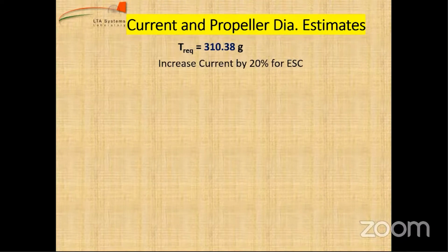So we start off with a thrust, and there's something more. Every electrical motor that you have. First of all, how many electrical motors do we actually have in our airship? Do you remember? How many motors do we need? We will need 3 motors. 3 motors, correct. Can you please quickly name the purpose of the 3? Sir, for 3-axis control, we'll need brushless motors. Yeah, so one for thrust, one for the lift or the attitude control, and another for the yaw, right?